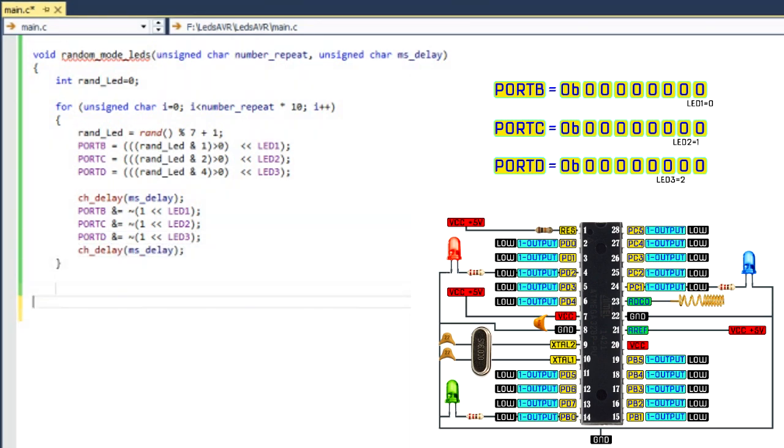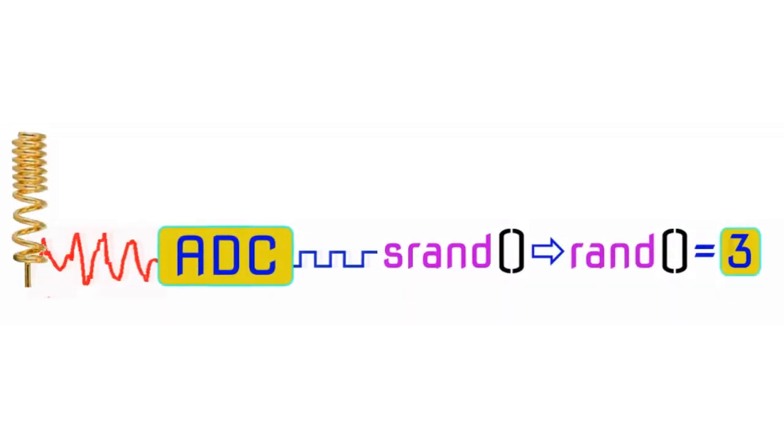To turn off all the LEDs. The rand function in C gives a pseudo-random number generator. The rand function uses a formula that calculates new random numbers based on a formula that includes the previously generated value. So where to get the starting point for the first number in the formula? The standard C library maintains an internal state for the random number generator, and the function srand can seed this state.